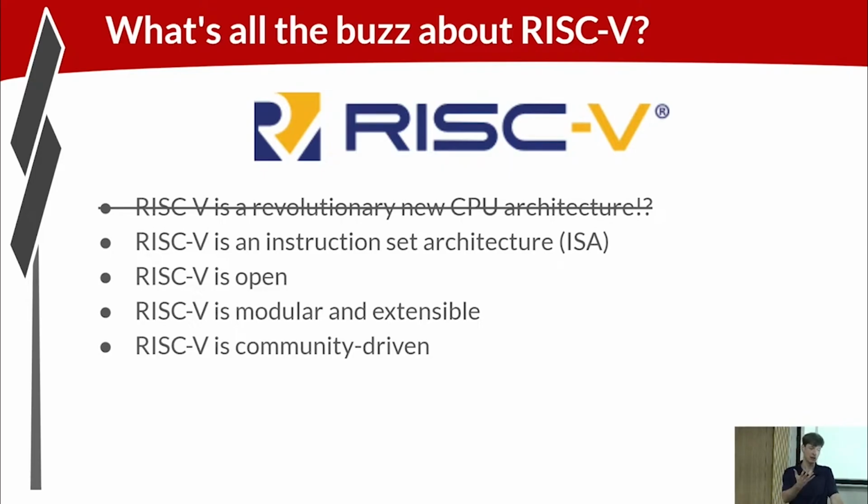If you implement a RISC-V CPU without support for the M extension, and the CPU encounters that instruction, it might take a trap to a trap handler that's going to do the software emulation of that instruction and then return execution to your code. So it'll function correctly. It won't perform those operations natively. It won't be performant for them, but it'll work. And so by layering on all these architectural extensions, you can implement cores with different characteristics that are appropriate in different circumstances.